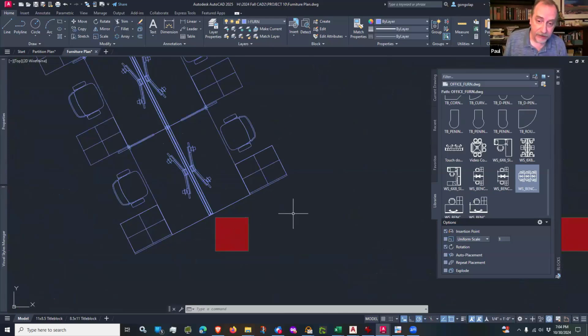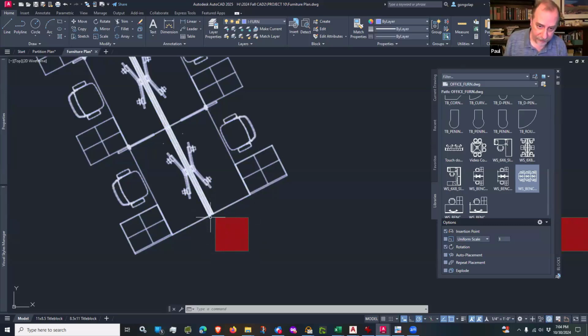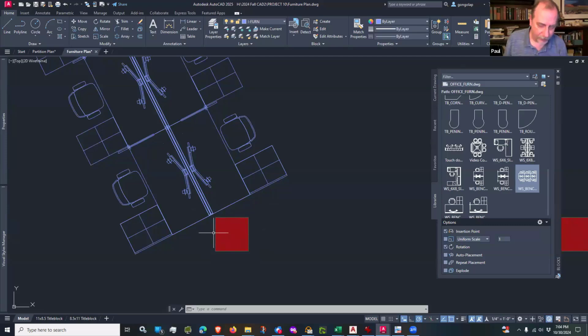So here's what happens. The power comes down from the ceiling through this column. This column has some furring around it. The actual column is probably a little smaller, and then there's some drywall furring around it. Or if the space is really industrial, then the conduit will come straight down to the ground to a junction box, and then there will be a flexible cable that will whip into the spine of the workstation.